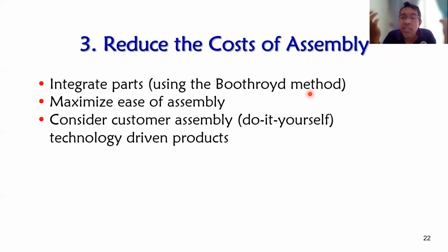So you can have a cost saving because the single complex mold or die used in this process is usually less expensive than two or more less complex molds or dies, and because there is usually less processing time, using this integrated part.